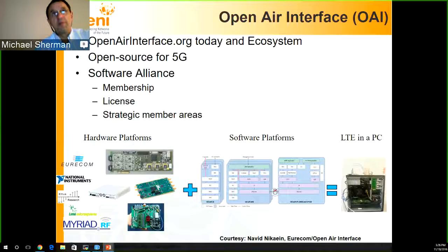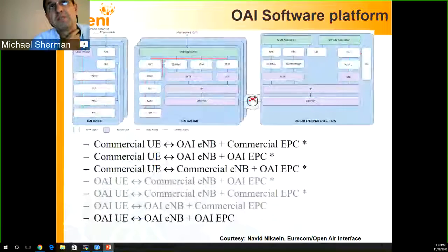implementations. Now, OpenAir interface is interesting because it's a full open source implementation of LTE that includes all three major components, the eNodeB, the UE, and the EPC. And actually, this slide shows you the partitioning of functions and literally the way we are using OpenAir interface in Orbit Testbed, and of course, it similarly could be used in other deployments to play with various aspects of LTE.